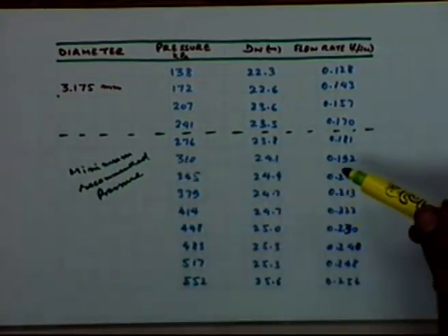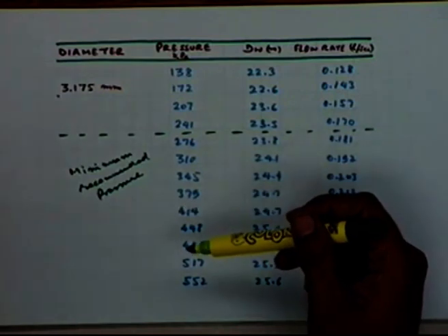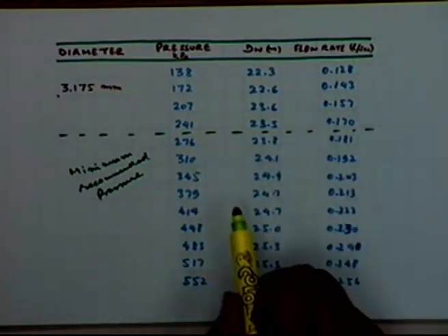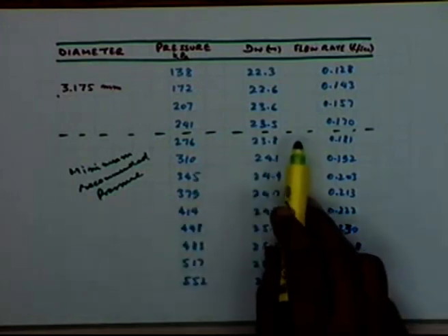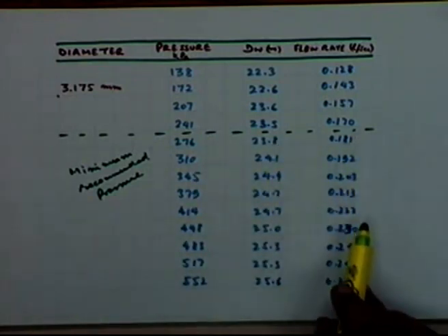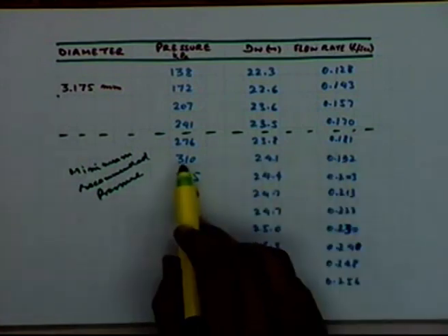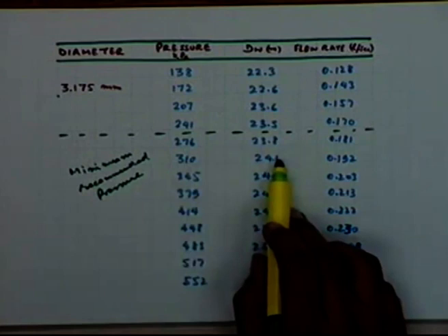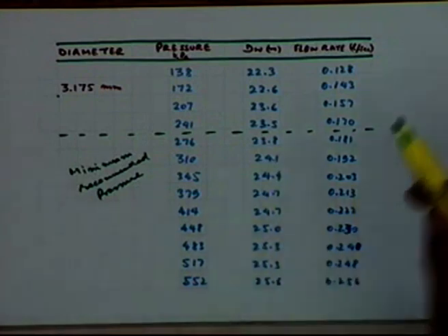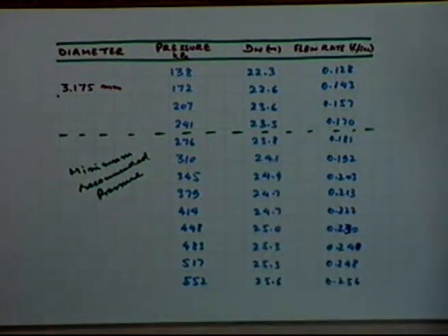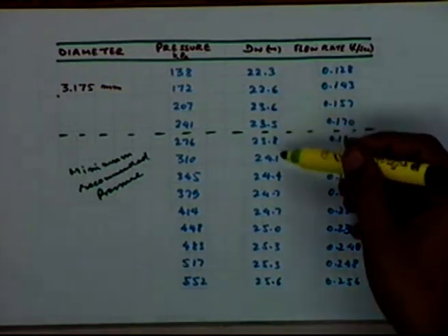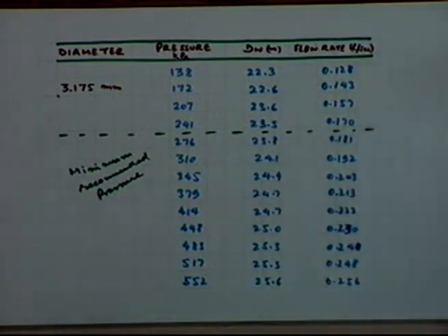You can choose with respect to the prevailing pressure available, how much can be obtained under the conditions, and accordingly what flow rate will be obtained if you run the sprinkler under this pressure, and this will be the wetted diameter. Now these wetted diameters are again the diameters without the wind conditions. If you have wind conditions, then there will be some change in the wetted diameter. Those things can be incorporated if you know the prevailing wind conditions.